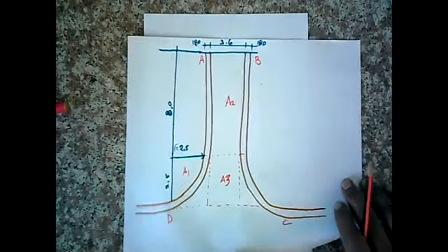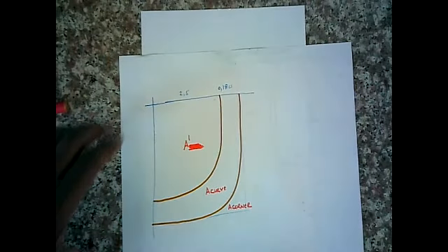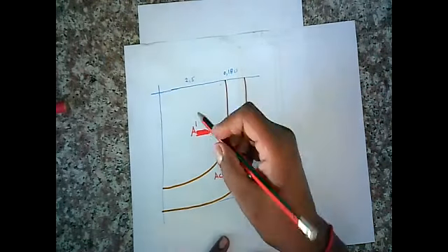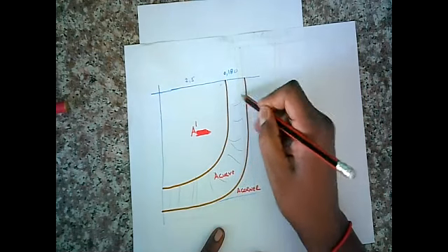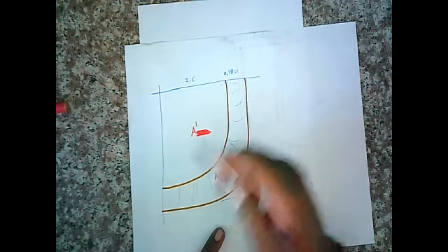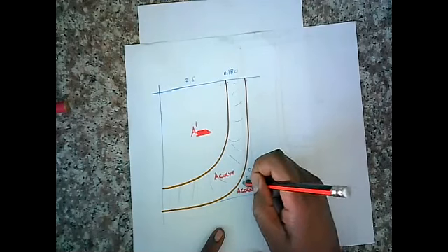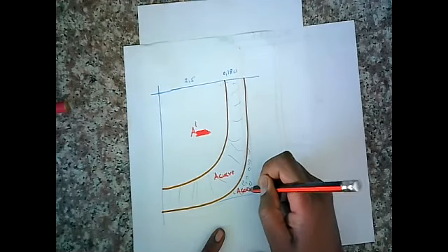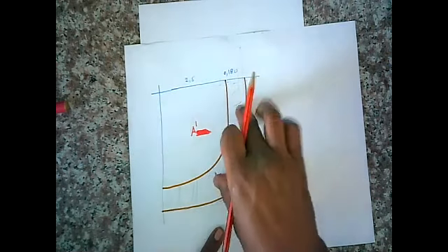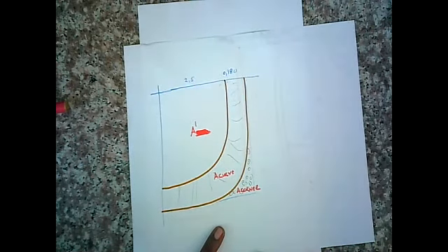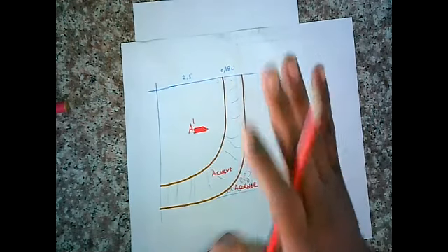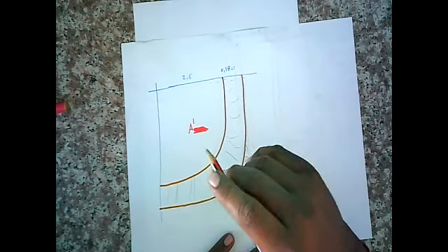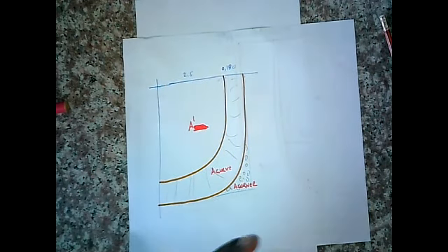All right. So let's look at A1. What are we trying to find? Here's your A1. I want to find this area of the curve bounded by the thickness of the curbs. And I want to find out this area here within the curve. Right, and what if I find on this side is times 2 because it's equal to the other side? This, understanding the sketch here, is literally, from my experience, the most difficult thing to do in basic roads quantification. All right, so let's start.